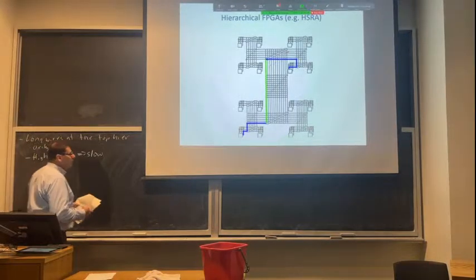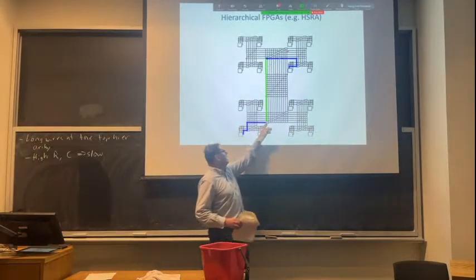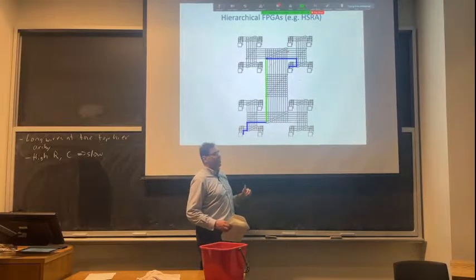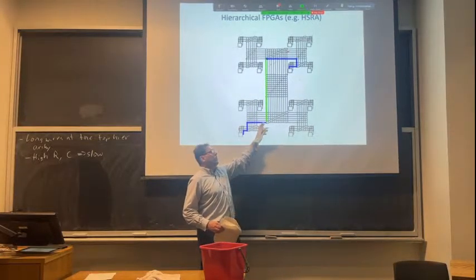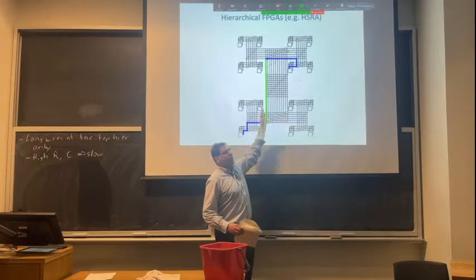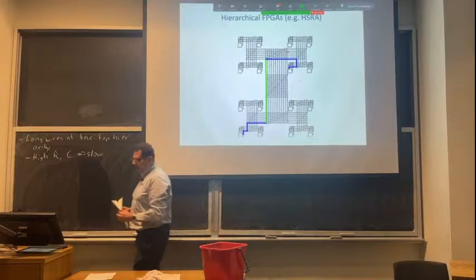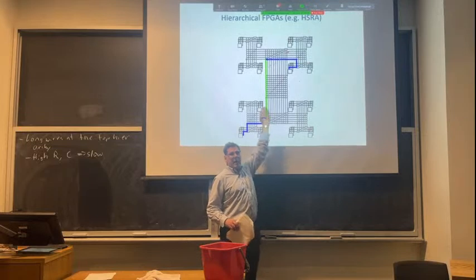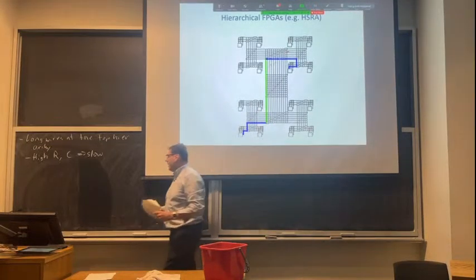So what we would do is we wouldn't really run a wire this far across a whole chip in a modern manufacturing process. It's too slow. So what do we do instead? Let's say I still want to have this architecture. What can I do with this wire? The problem is basically the longer the wire gets, the more its resistance builds up, the more its capacitance builds up, and its delay is proportional to RC.